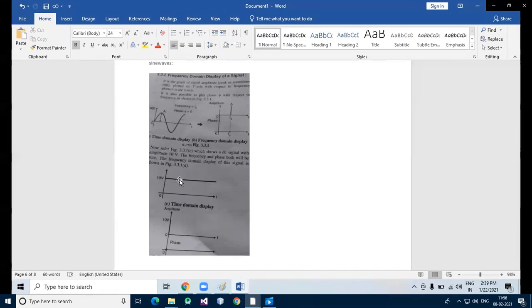Composite signal. Sine and cosine waves are the basic and purest signals, but they are not useful in data communication. Both cosine and sine are not used directly in data communication. To use the sine wave for data communication, we have to change one or more of its characteristics, such as amplitude, in accordance with the data to be transmitted.